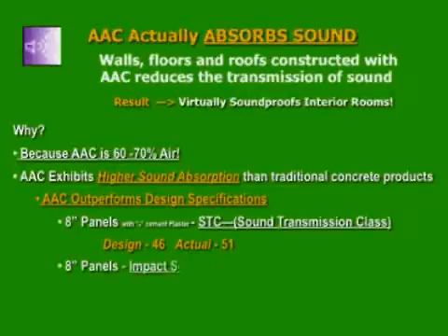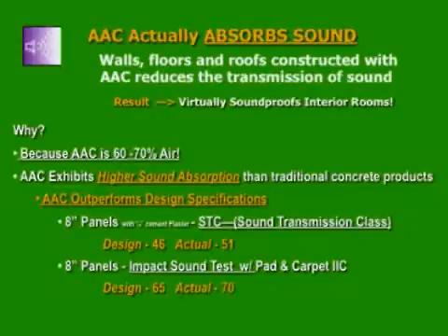The sound transmission class, known as STC, is a single number rating of the ability to resist airborne sound transfer at frequencies between 125 to 4000 Hz. Even with an STC rating, any penetration, air gap, or flanking path can seriously degrade the isolation quality of a wall. AAC has no air gaps and no flanking paths. AAC outperforms in all frequencies any other building materials of its weight per area ratio.